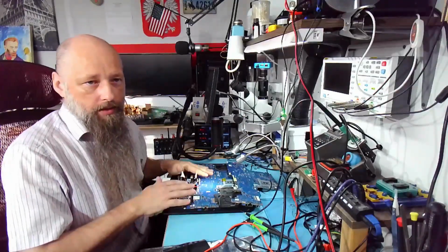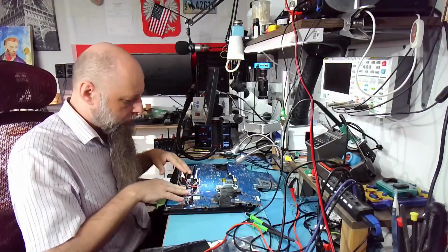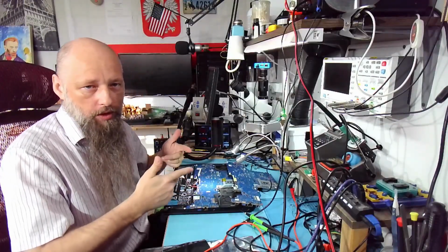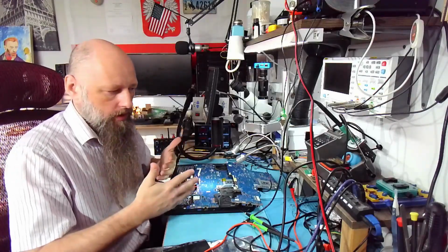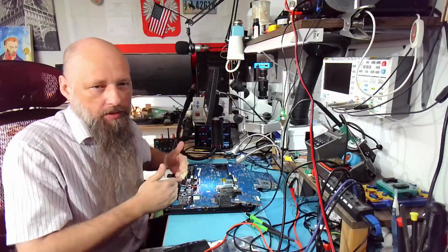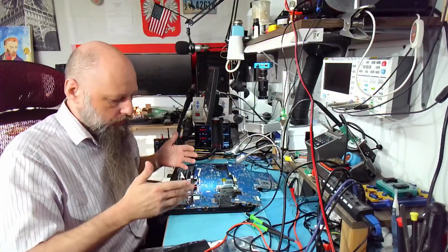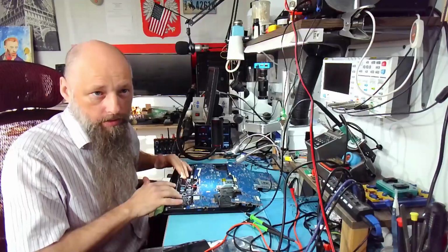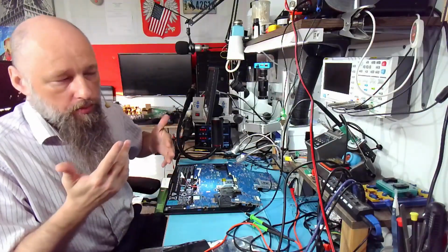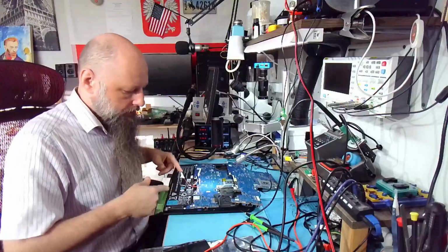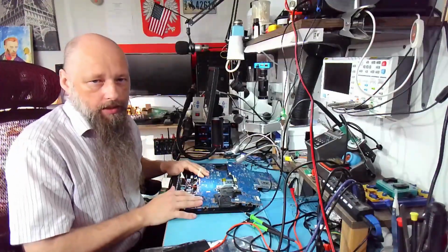So the battery can charge and it can discharge, the battery is fine. But there is only a spike of charging voltage and it drops, right? So typically that means that the computer decided that the battery is no good. And it will decide that if the battery is just different, the programming in the battery is different than expected.